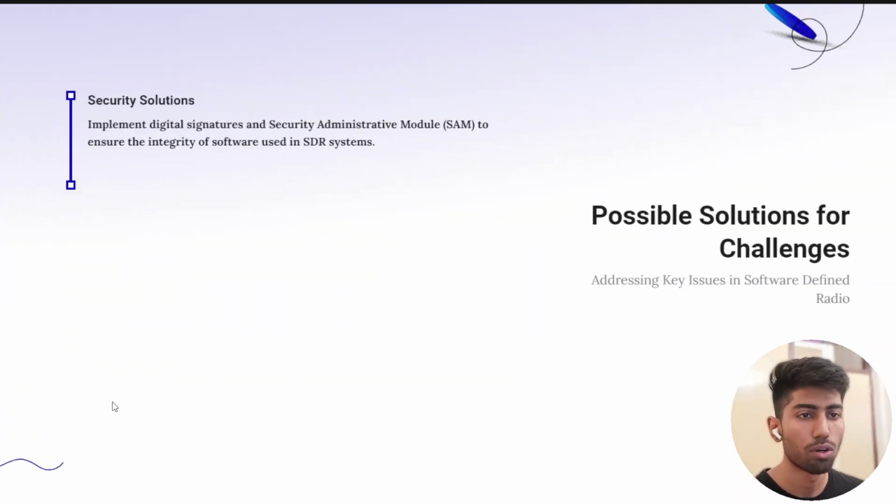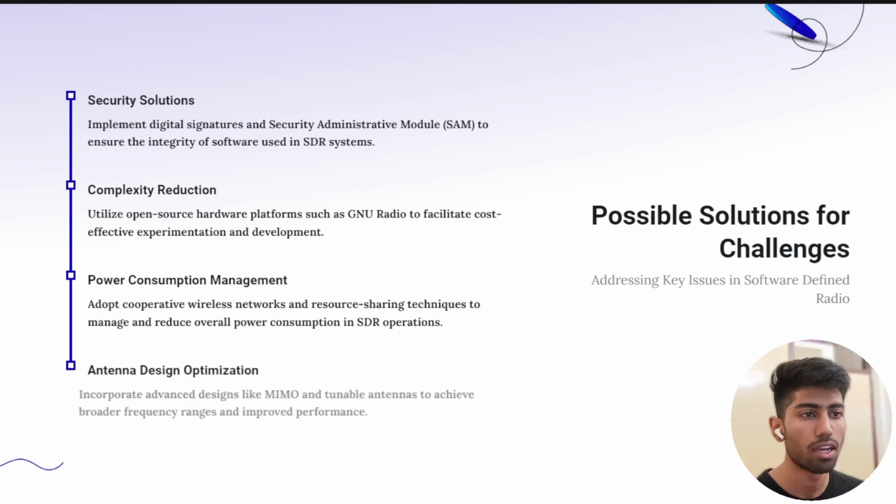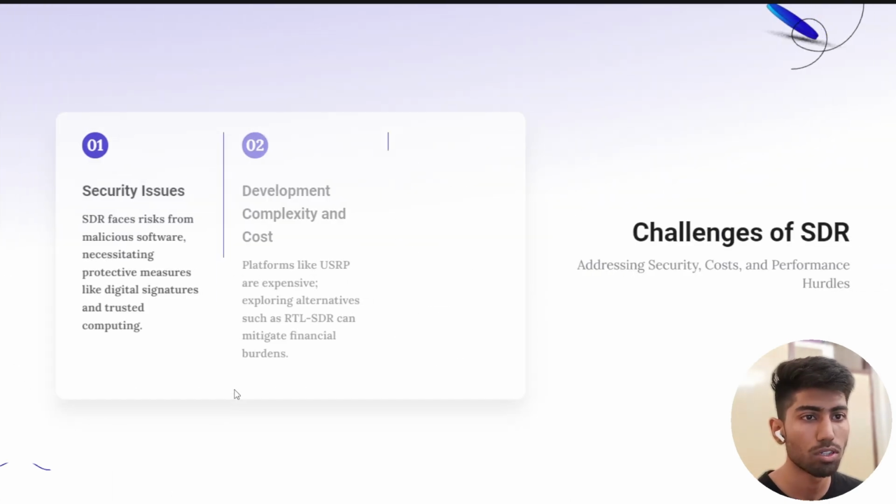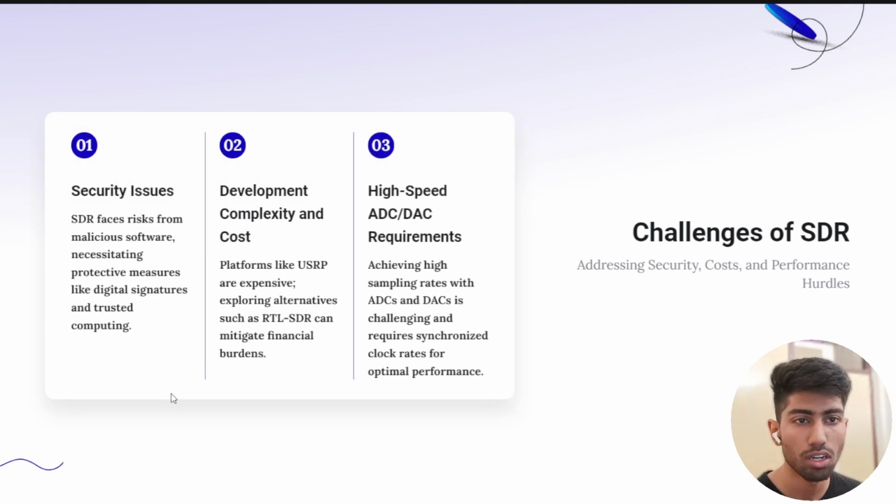Now, what are the possible challenges for SDR? The possible challenges are security issues, deployment complexity and cost issues, and the high-speed DAC to ADC requirement. Security issues arise because of software integration. In software integration, there is risk from malicious software, which requires measures like digital signatures and trusted computing.